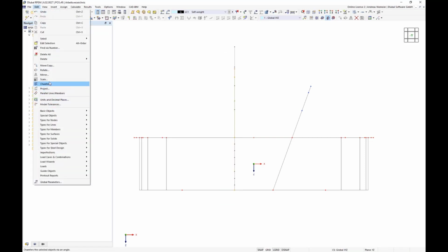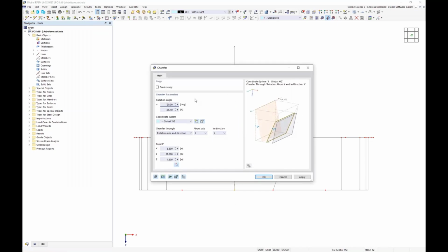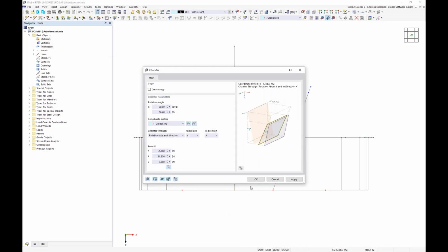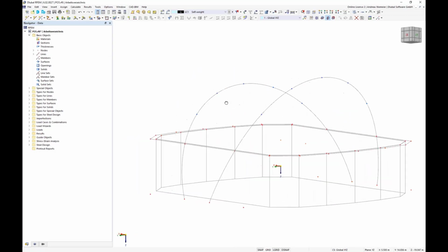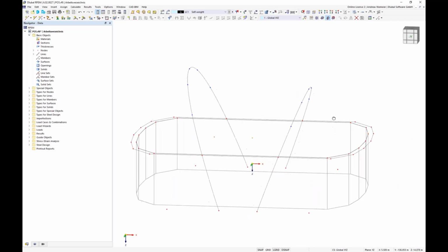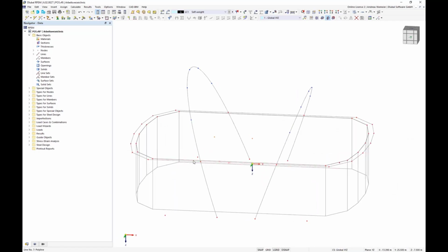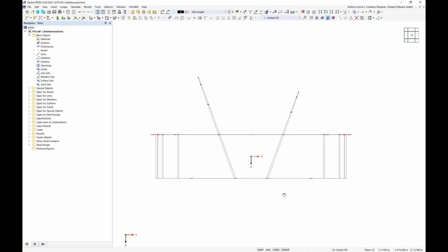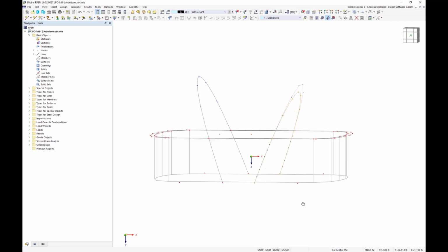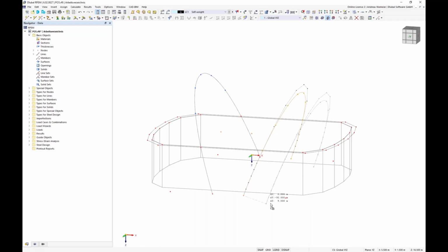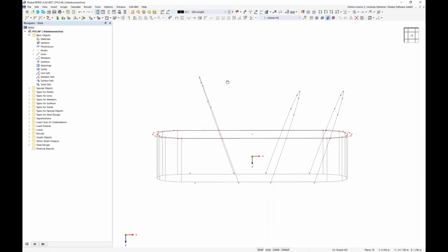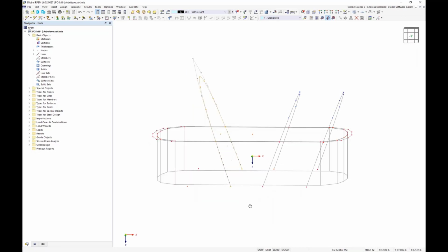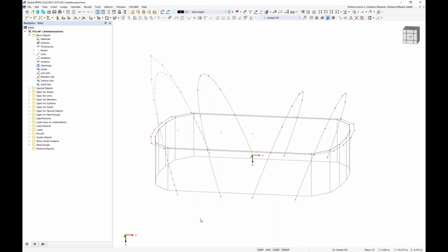We go to Edit, Camber. Now we have to change the direction and this rotation part, and with confirmation it will be moved in this direction. And this is now the state where we can say, okay, nice, we have defined these arcs, and it's ready to copy. So we can copy this geometry and copy it to the right place, and the same for the higher one: select it and copy it on the left side.